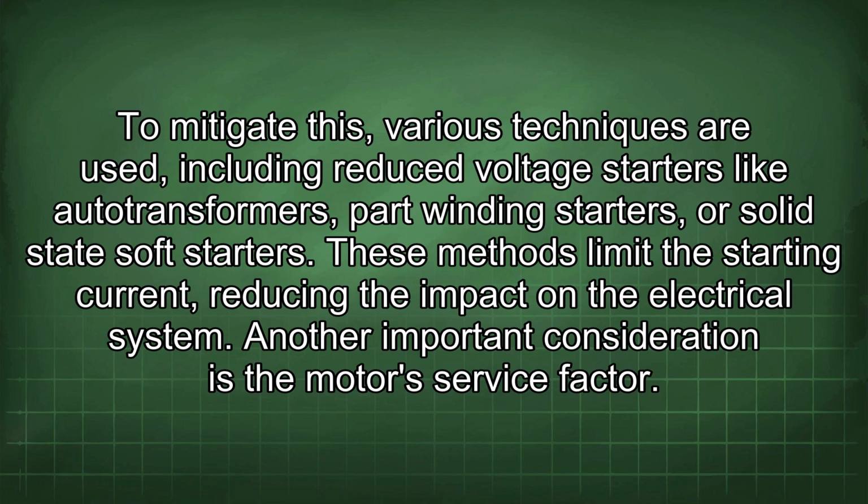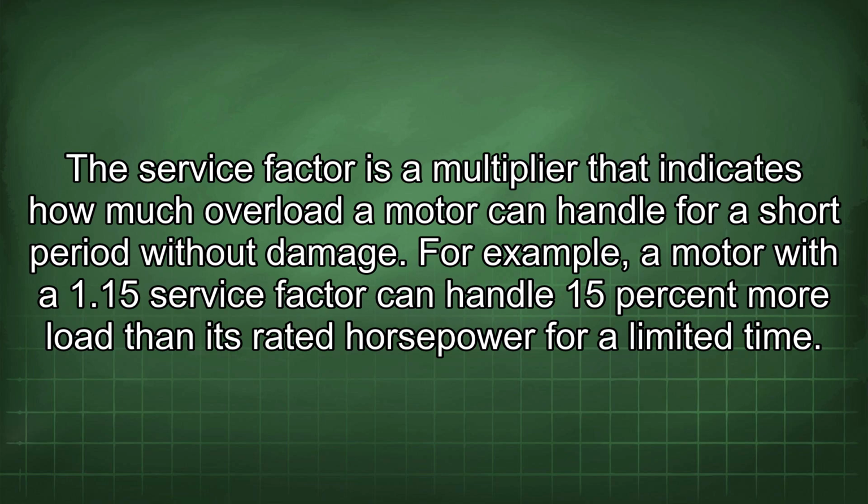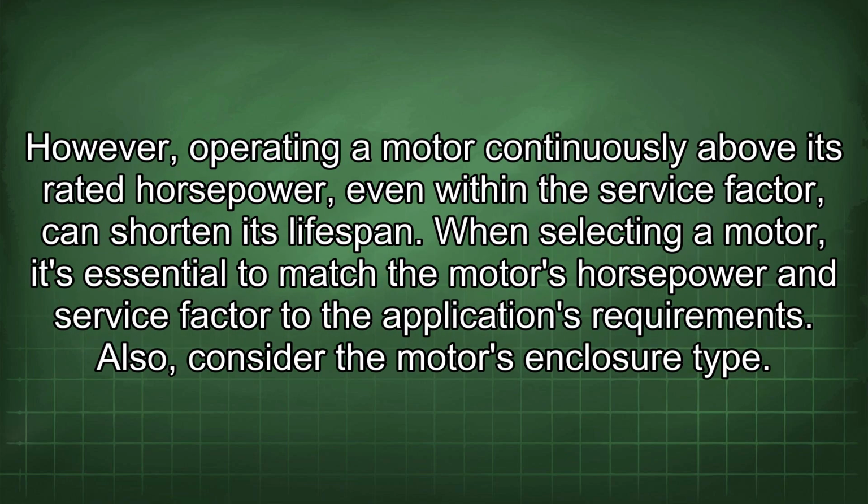Another important consideration is the motor service factor. The service factor is a multiplier that indicates how much overload a motor can handle for a short period without damage. For example, a motor with a 1.15 service factor can handle 15% more load than its rated horsepower for a limited time. However, operating a motor continuously above its rated horsepower, even within the service factor, can shorten its lifespan. When selecting a motor, it's essential to match the motor's horsepower and service factor to the application's requirements.